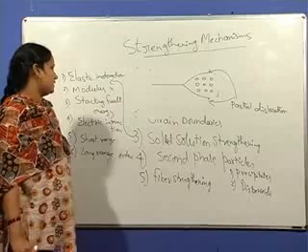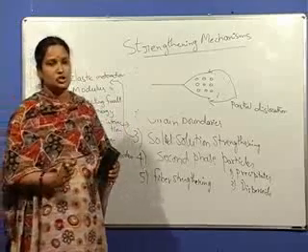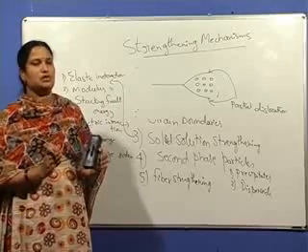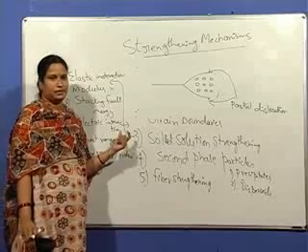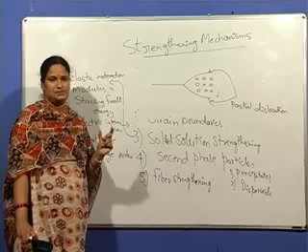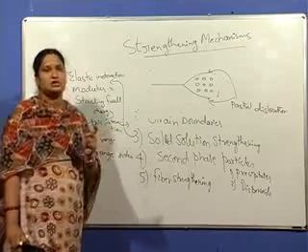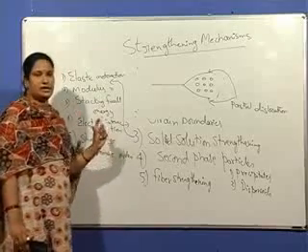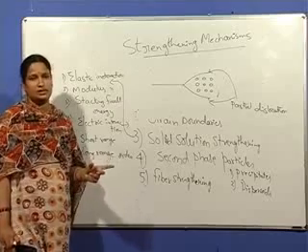Next is the electric interaction. The electric interaction mainly comes into the picture only when there is a large valence difference between the solute and the solvent. Because of this large valence difference, the electric charge is concentrated and localized on the solute atoms, and these solute atoms act as charge centers. These solute atoms interact with the dislocations, which have dipoles, so greater energy is required. So this is about the electric interaction. It comes into the picture only when there is a relatively large valence difference between the solute and the solvent.